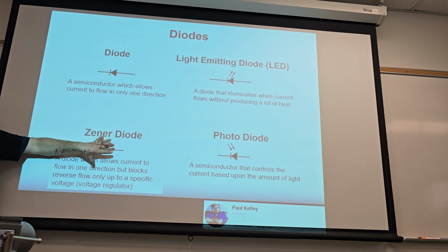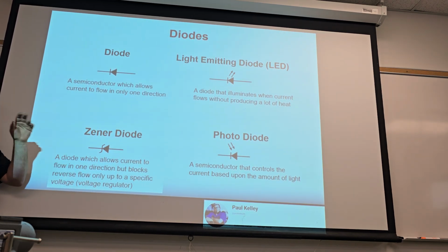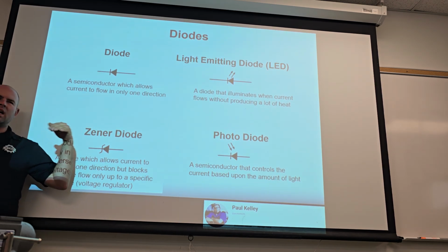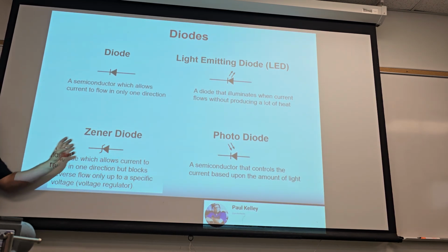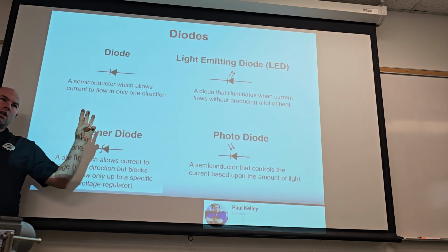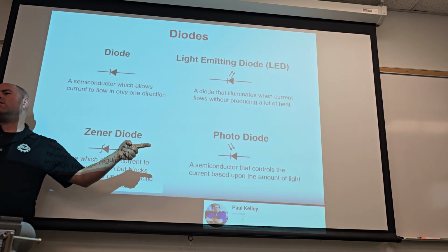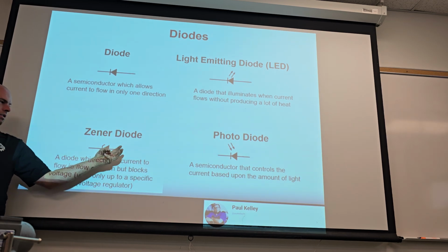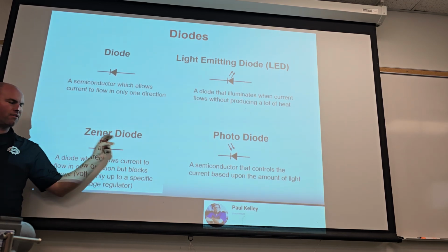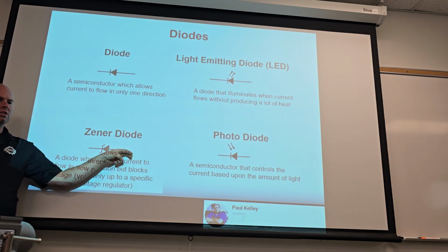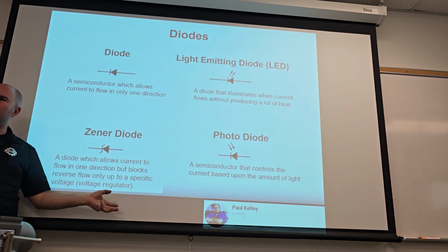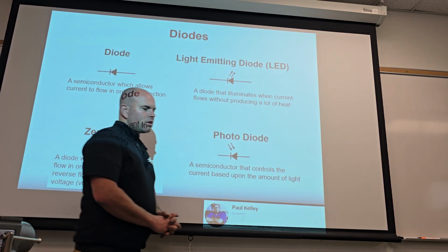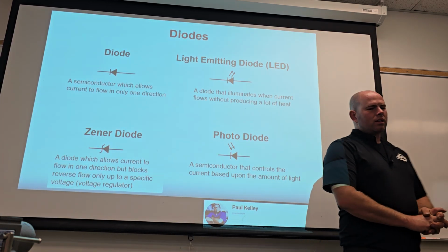So they'll do an arrangement of these, and a lot of times they'll use a 3-phase. We talked about the AC motors, right? But it'd be more like an AC generator, and they use several of these. At one point in the 3 phases, you'll be getting over 12 volts, but on the other phases you may be getting under. So these would block the 2 phases and allow the 1 phase. Then by the time the 12 volts starts to get low on the 1 phase, another one's coming up, right? So we'll actually use something like this in an alternator with an internal voltage regulator.